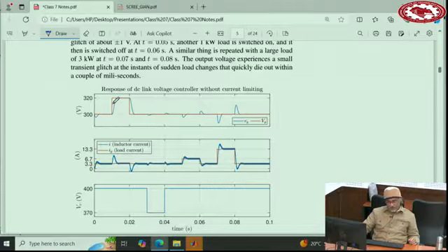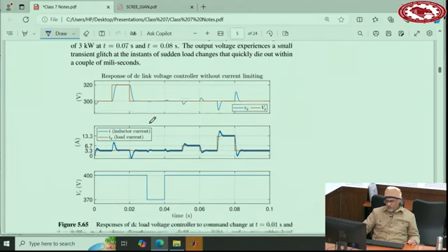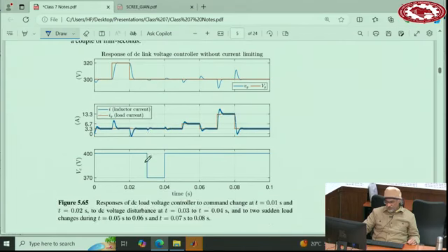And then you will see, yes, it clearly follows, with almost the same time constant that you had expected. And the transients and oscillations are great. You don't have any extra oscillations here. And then come back to 300. And here, let me see what kind of disturbances I have applied. At this point it's clear because I have applied a disturbance on the left side. The voltage drops from 400 to 370 and then back again to 400, and you see almost no change, a little glitch, and that's it.